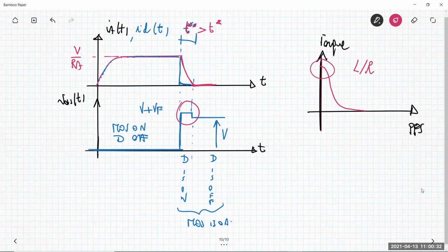Remember that we saw a graph of this torque versus pulse per second in the slides provided by a manufacturer, which exactly states this behavior. Okay, which is a very poor torque behavior versus frequency, due to exactly this very large turn-on and turn-off time interval.